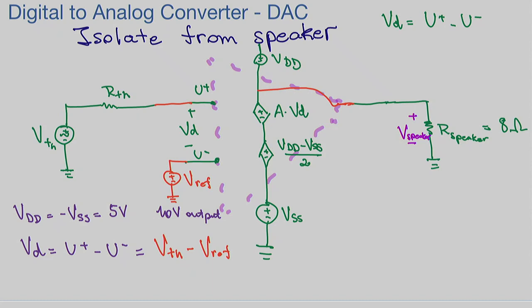So it's the model of the op-amp. We have those two leads. Those two leads are modeled as an open circuit, and in an open circuit we know the current is 0. That's always the case, by the way. And we will see that this even has a special name for op-amps.